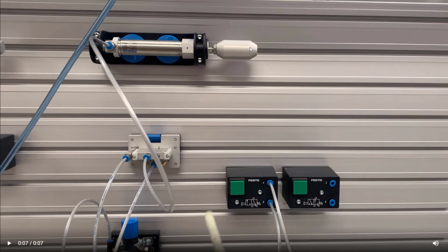I talked about this in the online lab, but take a look at this. This guy over here, that's fine. This guy can go back in its normal state and no longer make pressurized air come out of here. But for this thing to come back, the only way that's actually going to come back is if you put air in here and make it come back, or there's some other force that makes it come back. Yeah, and that's a spring inside because we know there's no air going in here. That's actually just an exhaust port.